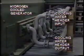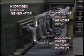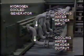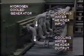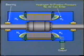The heat picked up by the hydrogen is extracted by passing the gas through water-cooled heat exchangers. Some adjustment of cooling water flow through the hydrogen coolers may be necessary to maintain optimum temperature of the hydrogen gas. This is normally performed automatically. As the hydrogen is maintained at a positive pressure inside the casing, there is no possibility at all of air entering from outside. This is a distinct advantage, as it ensures that the generator internals operate under ideal, clean conditions.